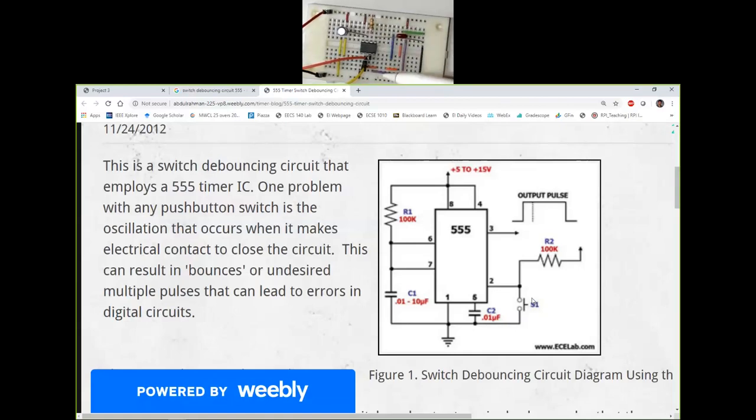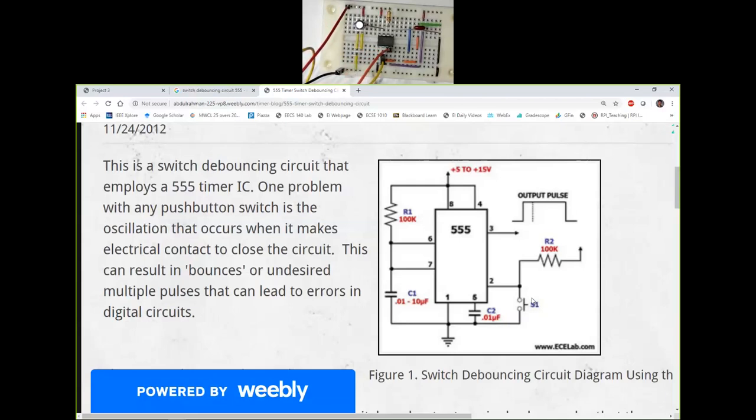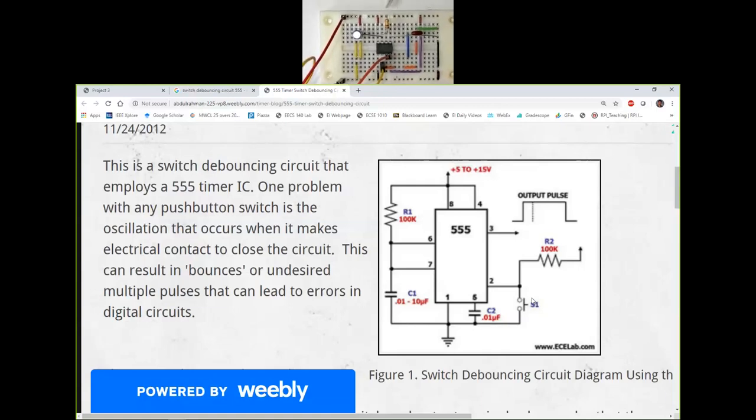Pin number 7 is connected to ground using C1. We have found out the value of C1 to be 1 microfarad. So this is the 1 microfarad capacitor that the positive terminal is connected to pin 7, the negative terminal is connected to this point, which by using these two yellow wires is connected to the ground rail, which is the bottom rail here. And then of course you have pin 8 connected to high using that red wire there. So that's essentially how I put together the circuit.